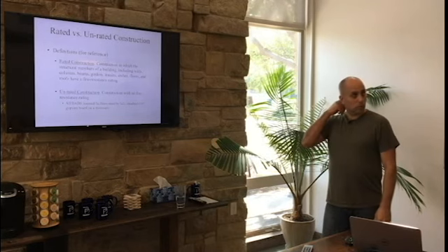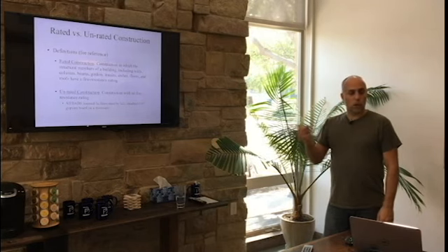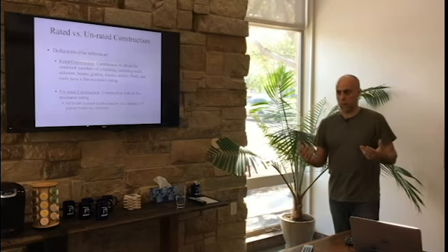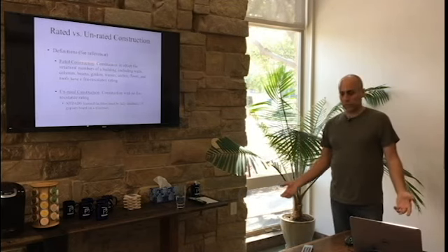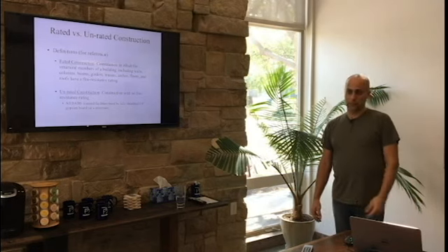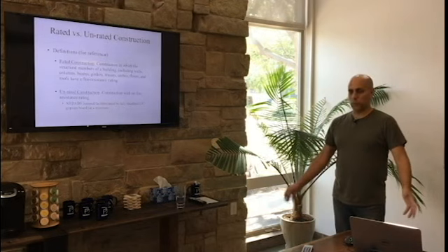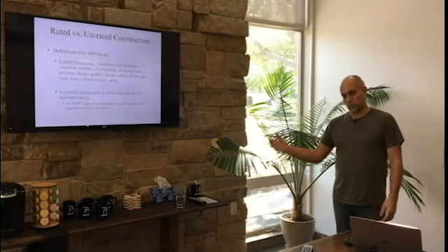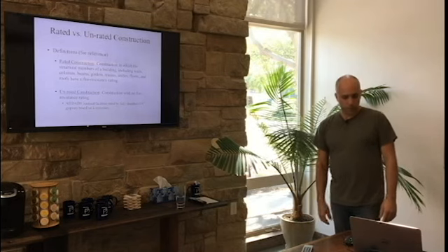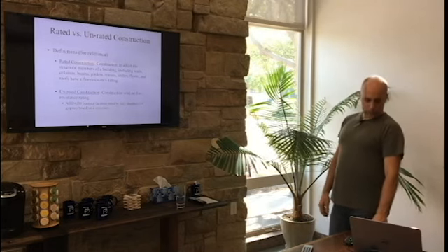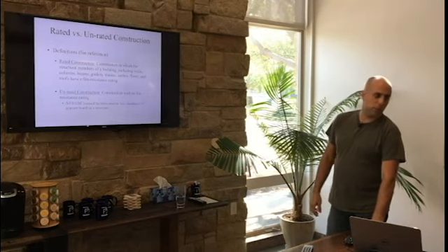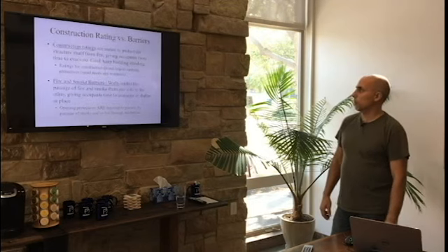Even in a conversion of a home to a small facility, which is not something that we do as a firm very often, you have to at least have gypboard. You can't just put up plywood siding on the inside of your walls and call it good. At a minimum, you're going to have to put up gypboard. They do sell 1/4 and 3/8, but typically you're going to see 1/2 inch or 5/8 inch gypboard. So as a rule of thumb, all of our facilities have 5/8 inch gypboard, period. Even if it's not rated, we do 5/8 inch gypboard because it's a minimum sheathing requirement.